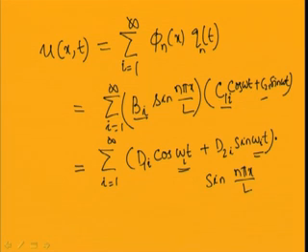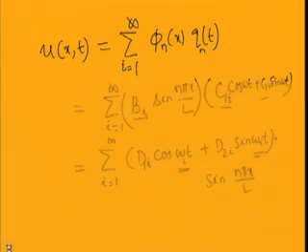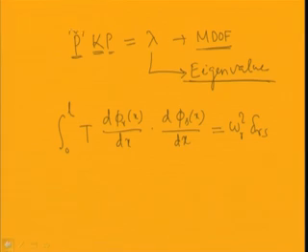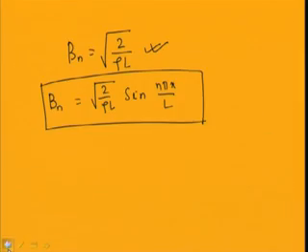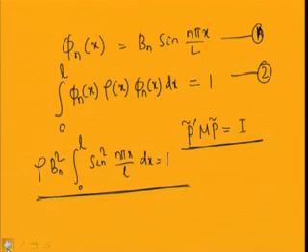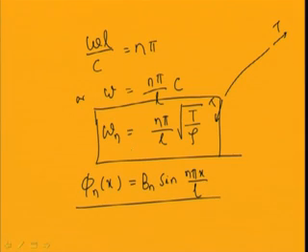So, already you know the relation between this omega for different mode shapes, different modes. For different modes you have already found the expression for omega for this transverse vibration of the string, and this can be written in this form: omega_n equal to n pi by L root over T by rho.